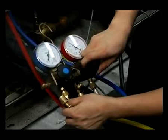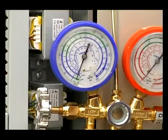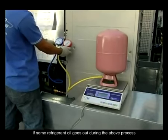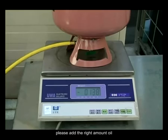If above problems exist, please discharge all the system refrigerant and vacuum the system. Recharge the refrigerant when vacuum rate is reached. If some refrigerant oil goes out during the above process, please add the right amount oil.